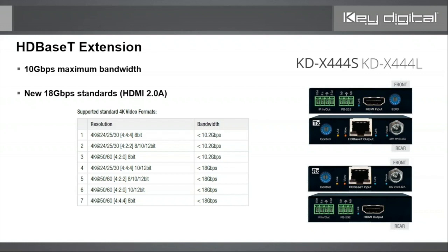And those new parameters added on to an already extremely heavy signal took the existing 10G bandwidth of HDMI, and now a new source that's just outputting everything at the highest level can have content that results in 18 gigabits per second. And this created a huge problem.